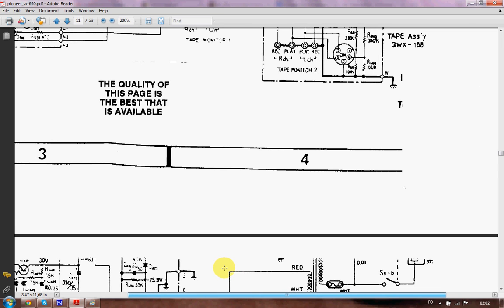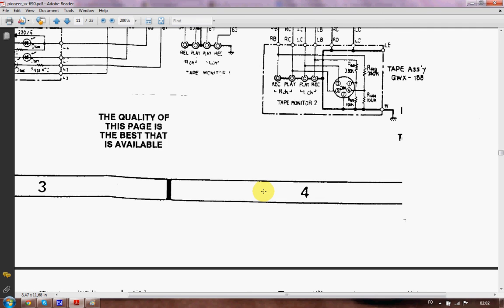So as a conclusion to what I've just explained, look for the easiest and most obvious things first. A visual inspection of all the soldering joints. Do you have a blown joint, or does the circuit board have a leaked capacitor, or has flux from the solder deteriorated the material of your circuit board? Have the current carriers broken or deformed so badly that they could have broken?